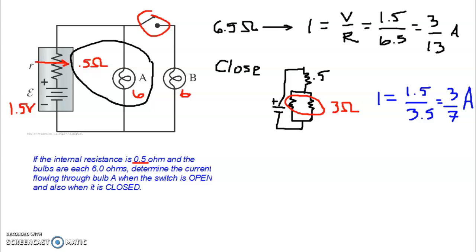So it kills the battery in the short term, if you keep doing it, making it drive current through a small resistance load. For large resistance loads, that 0.5 ohms would never show up. No one would care about it, and the battery wouldn't really heat.